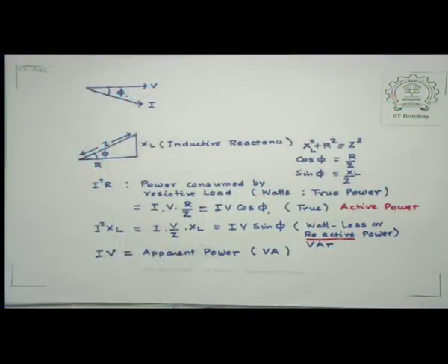Now, you notice this apparent power is more because the current and the voltage are out of phase by an angle phi. And reactive components, like the true components, also draw power, but however they cannot use it for doing any useful work. What they absorb in one part of the cycle is returned to the source in the other part of the cycle. What we do is to observe that this power triangle therefore becomes like this.